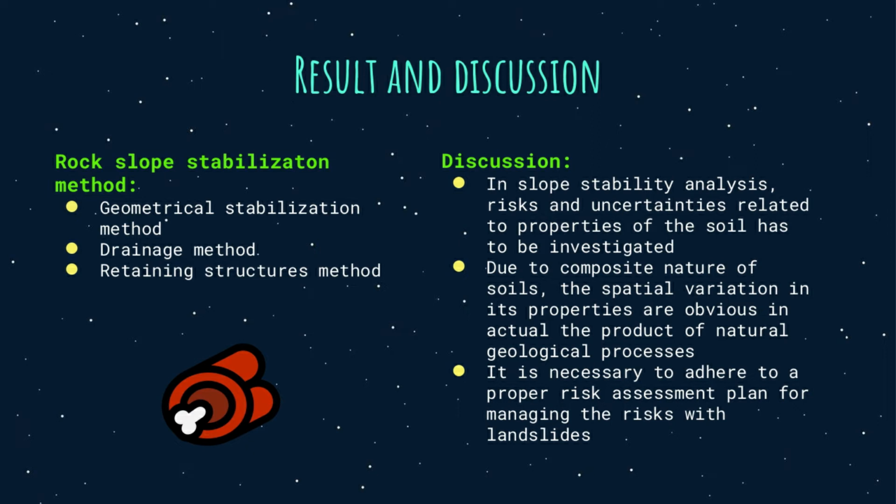Following the identification of the reason for slope instability, the most appropriate slope remedial measure is chosen based on feasibility, stability, and cost. There are two slope stabilization methods that have been identified. First is the geometrical method. This is the most popular strategy, where the procedure is usually straightforward and inexpensive. The stability of the slope can be improved by altering the slope angle from steep to mild, and the angle is usually supported by grass bonding with the soil.